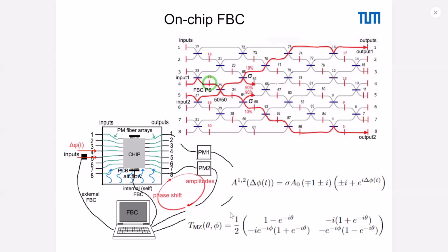Okay, so we propose to use such a scheme. So what do you see on the scheme? Yes, we are quite lucky because the photonic processor actually has a lot of phase shifters, which we can use to control phase and actually use it like a self-feedback control. So use one of these phase shifters to fix our phase difference. However, we have to somehow measure this phase difference, and this is the scheme we first propose for measuring it. We use one phase shifter, 2 inputs, a 50-50 beam splitter, and outputs 1 and 2, like an amplitude measure,